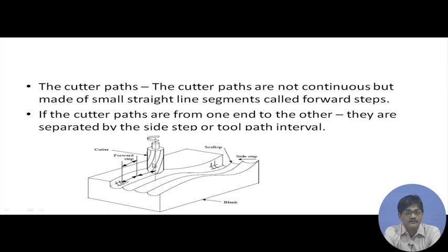Forward steps are tolerated through form tolerance; here the side steps are creating surface roughness, and we will have a tolerable value of these upraised portions, so that all of them either remain within a tolerance value, or preferably all of them are of equal height everywhere, which is much more difficult to attain.